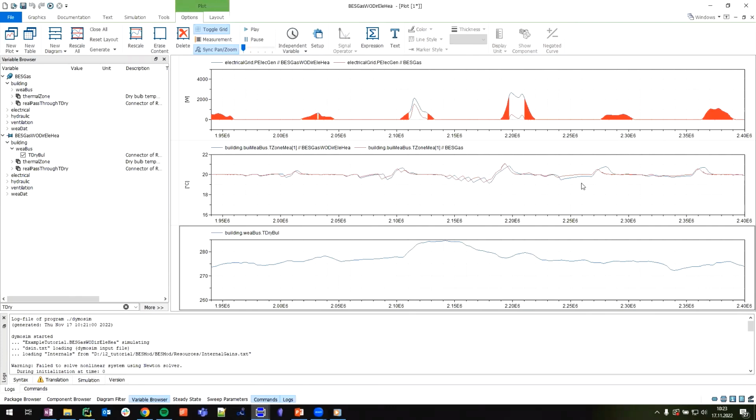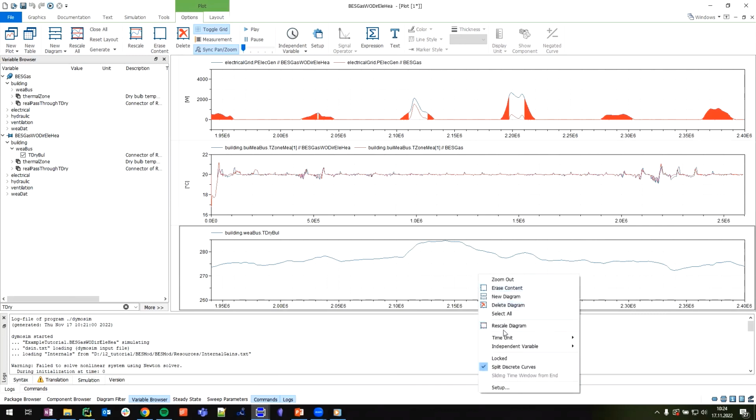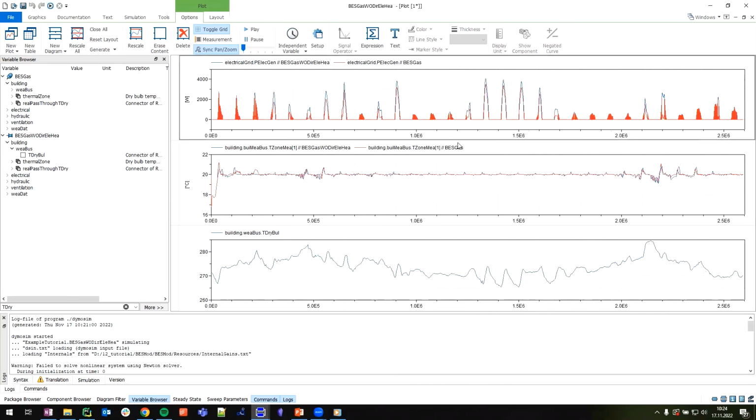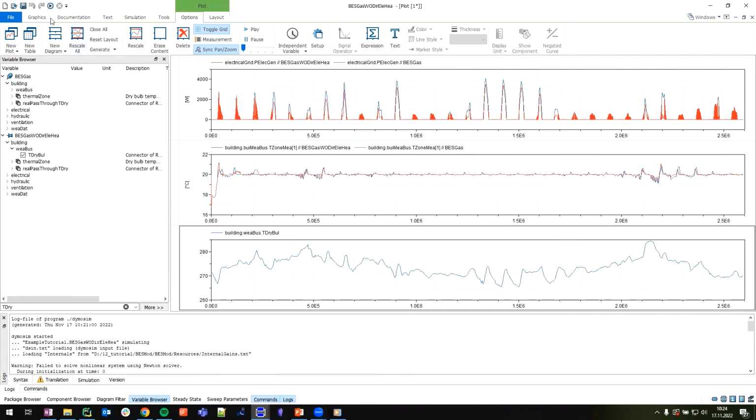So what we could do is, for example, increase the set value and say, okay, if we have surplus of PV, we can increase the room temperature to 22 degrees Celsius or something, and use the building mass for inertia and demand side management. Also, we definitely would have to improve the hysteresis of the model, but this again does not show how direct electric heating could be beneficial or not. It just shows you how to add a module to BESMod.